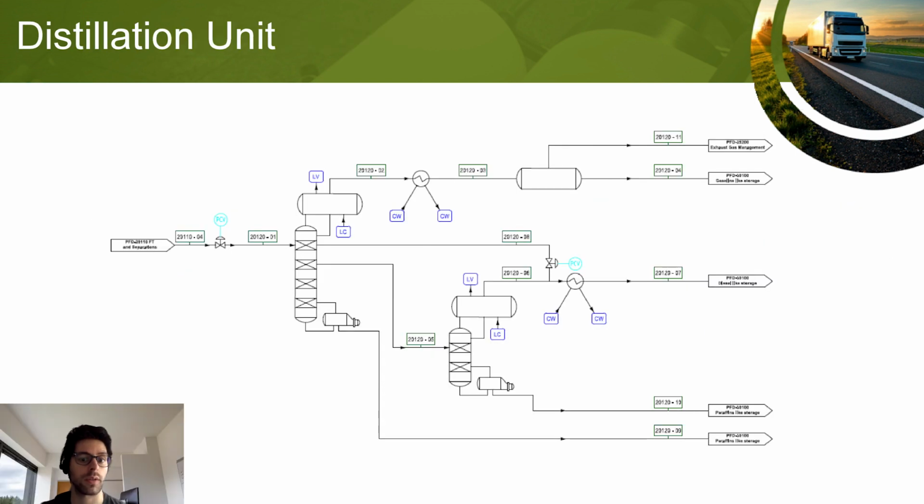The distillation columns to separate the different syncrude cuts had to be very high to have an efficient separation. So we had a column that was about 40 meters high, while the column diameter only had to be 0.2 meters, which is constructible, but definitely not optimal. So we decided that the syncrude should be directly transported to an already existing crude distillation plant, handling much bigger flow rates, so they could mix this syncrude with their normal crudes.